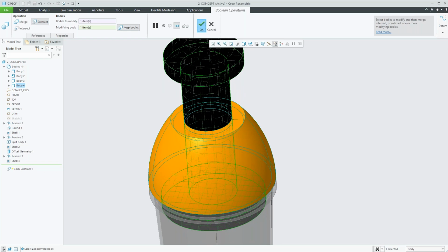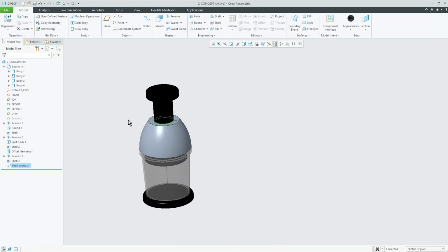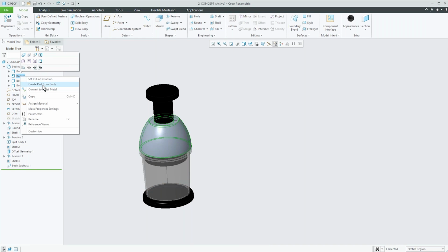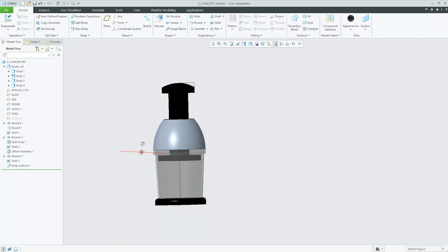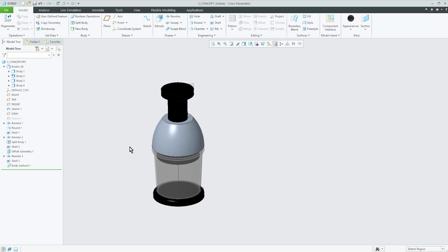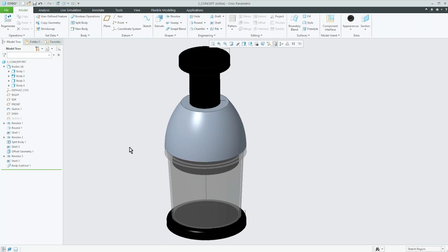So now I've created really quickly 4 different parts, and now I can go through and maybe extract each one of these out as a part, and then put them in an assembly, because potentially I'm going to want to create maybe a cylindrical joint in here so I can actually activate this and move it up and down. But again, this is allowing me to create in a single part file, from where I've derived a sketch, an idea, and kind of broke it into multiple parts.